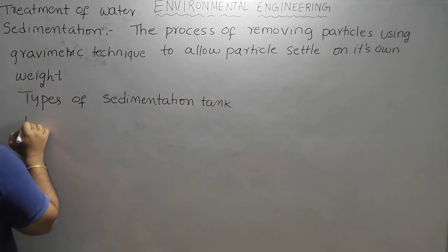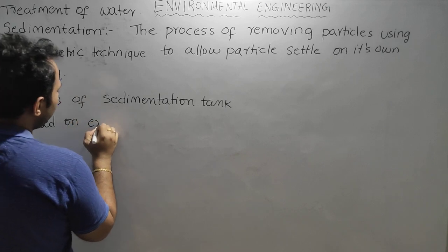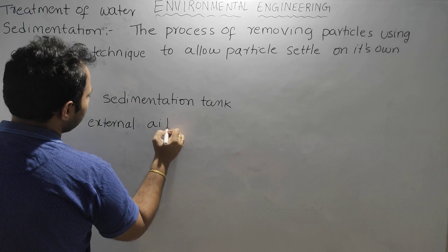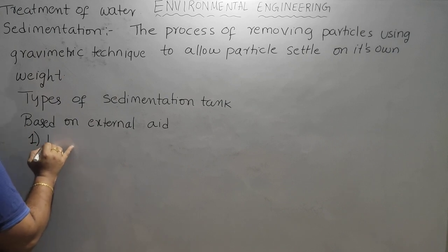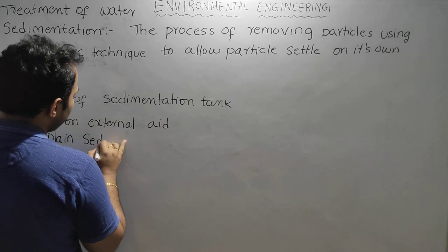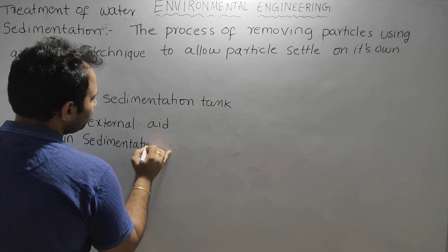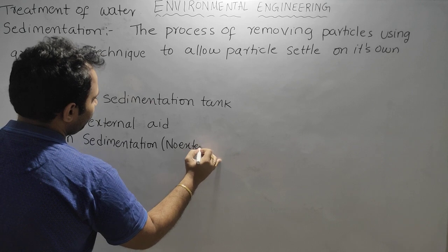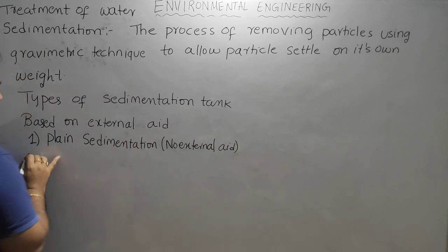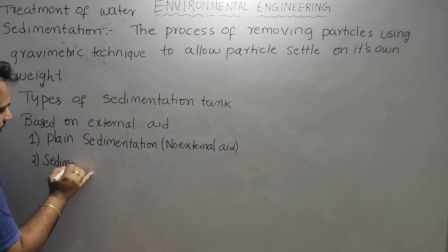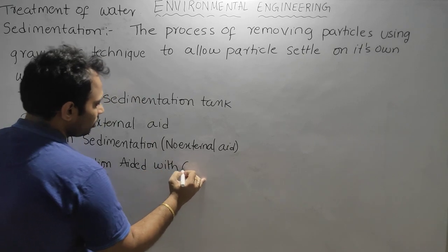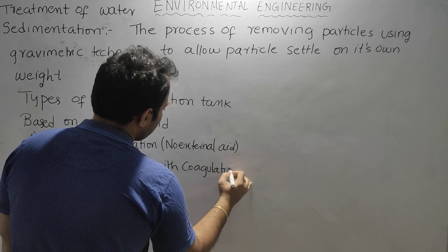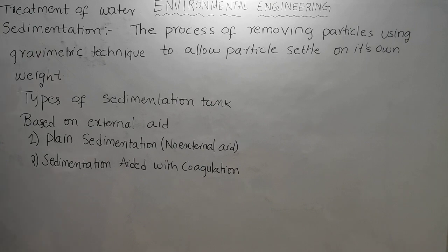If you are helping it from an external source, then it is sedimentation aided with coagulation, where we add coagulant externally. If no aid or help is given to the sedimentation tank externally, that is called plain sedimentation.